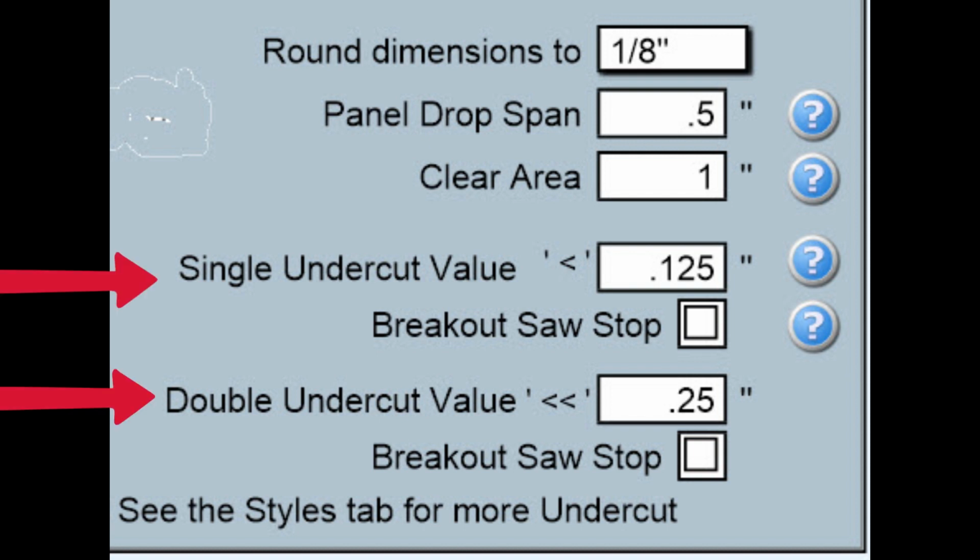Many components allow you to indicate they should be undercut from the stated dimension. When a dimension is shown, click on the left side of the dimension field to change the undercut indicator. Enter 0 here in Preferences to cause the undercut indicator to appear on cut sheets, or enter a different value here to cause them to be undercut by that amount. 1/8 and 1/4 may be common. Foam includes the letter V to indicate the foam should be cut to size or larger to assure a tight fit. Undercut values do not change times, prices, weights, or relative dimensions of other components.